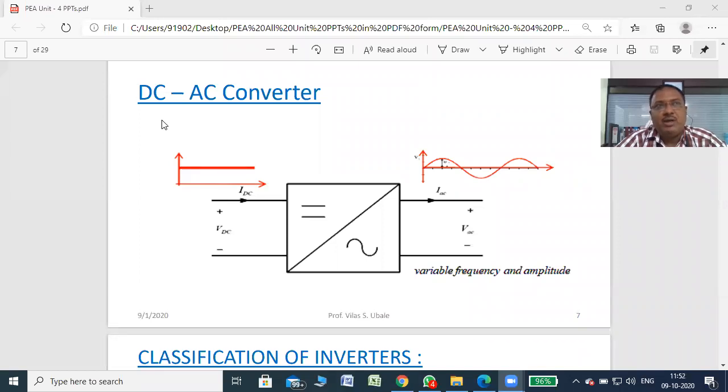We have a supply voltage with a line frequency of 50 hertz, which is a constant. You may have a variable voltage by using some circuits, but to control the speed of AC drives, we require variable frequency, not a variable voltage. So to obtain variable frequency, we require a circuit called an inverter, right? Inverters may be driven with the help of DC batteries or AC converted to DC. So both can be used.